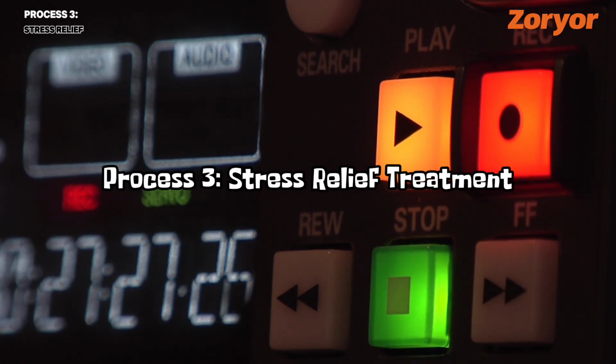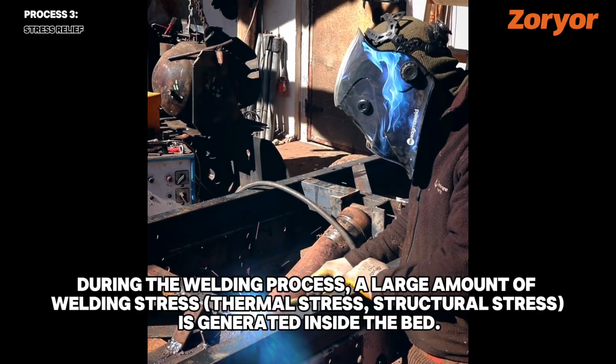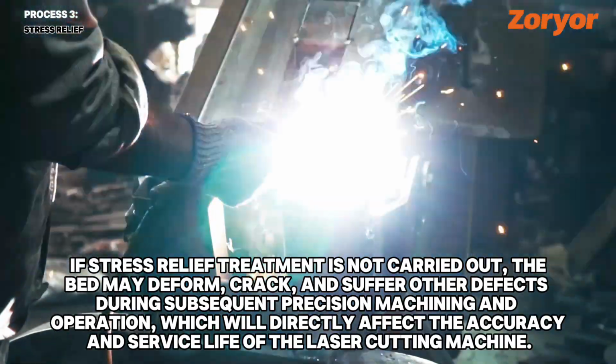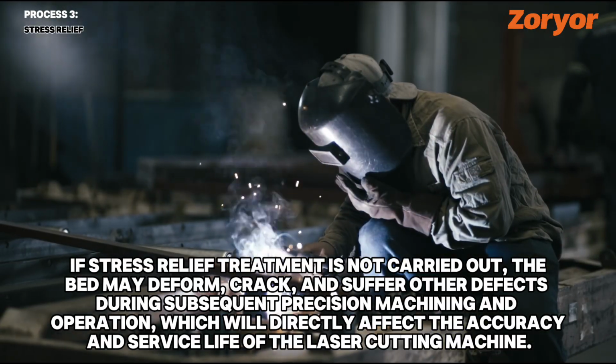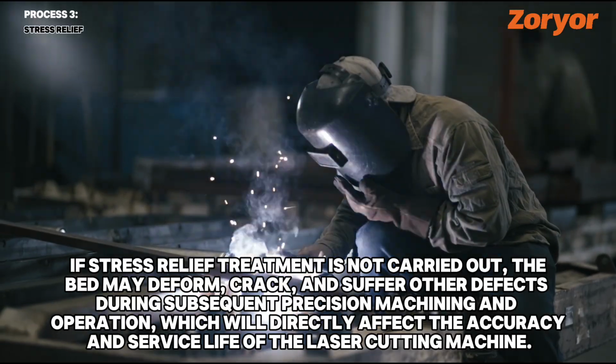Process 3. Stress relief treatment. During the welding process, a large amount of welding stress is generated inside the bed. If stress relief treatment is not carried out, the bed may deform, crack, and suffer other defects during subsequent precision machining and operation, which will directly affect the accuracy and service life of the laser cutting machine.